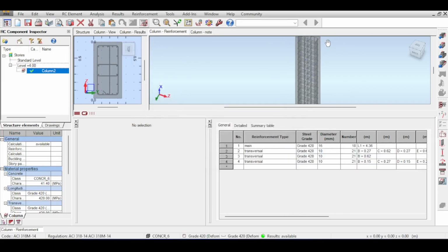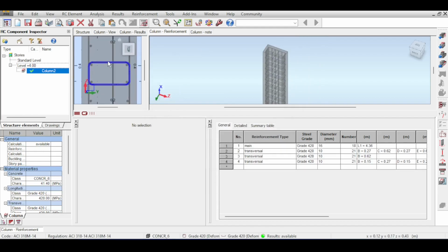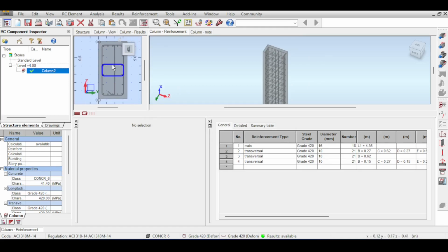Now, the final thing I wanted to talk about is the stirrups. Now, ACI code asks you to confine your longitudinal bars to stirrups, and there is a very good code requirement for this that says that if you have bars, you are allowed to have one bar being confined with the corner of a stirrup and one bar not, one bar confined, one bar not. You can see that the column fulfills this requirement, and if your spacing between the bars is I think more than 20 centimeters or 200 millimeters, then all of those need to be confined.